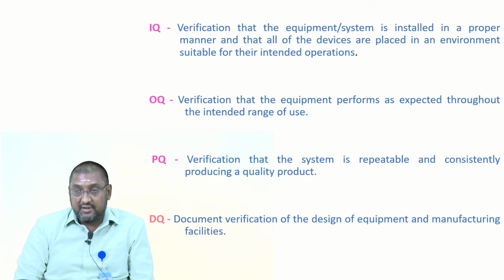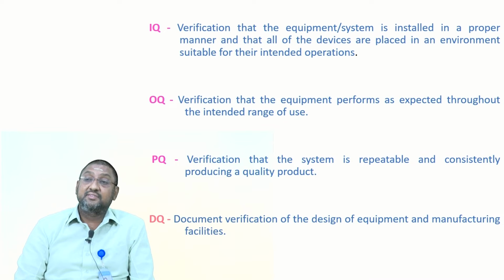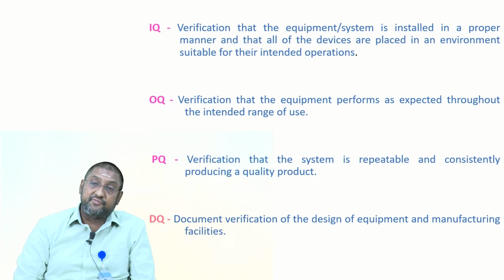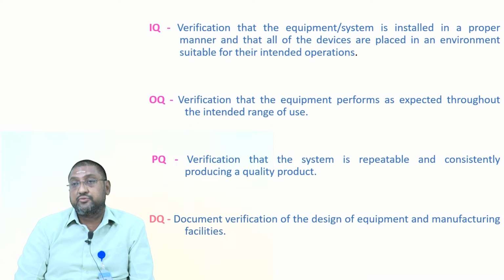Suppose you purchase a 28 station tablet machine; you have to get the manual and install it according to its instructions. Once you purchase it, if you want to install it on the first floor, you have to ensure whether it is capable of being installed there. So, as per the installation procedure, you do the installation qualification. Then operational qualification.